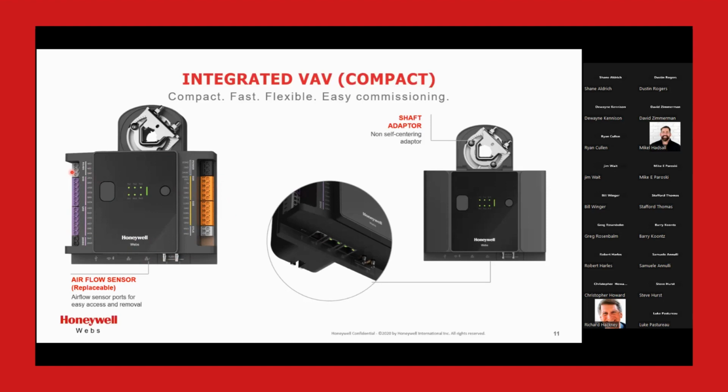This controller, the VAV and the unitary Spyder 7, all incorporate both a Silk subnetwork and a Modbus subnetwork. So if you look at the picture here, this is way more than what you typically find in a Honeywell VAV controller. It's got a boatload of I/O. It's got Modbus. It's got the Ethernet, the user replaceable pressure transmitter, the feedback on the actuator.